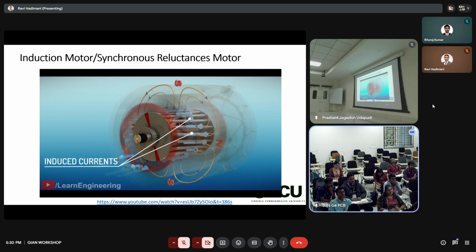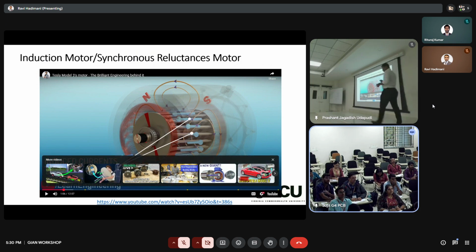which in turn generates currents in the rotor bars. So the induction motor, okay, this is the Model S, the older model of Tesla. They have soft magnetic materials. Induction motors should have no coercivity. Otherwise, if you cycle the field to get induction B, and if there is coercivity, energy is lost.